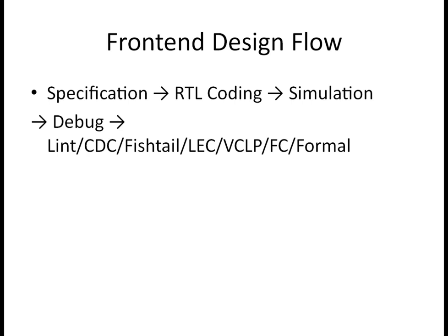Sim to sim means synthesis versus simulation, where we are checking that the RTL which is going for simulation and the RTL which is going for synthesis should be the same. That should not change. So we'll be giving input to the tool, the RTL, in a different flavor of RTL.